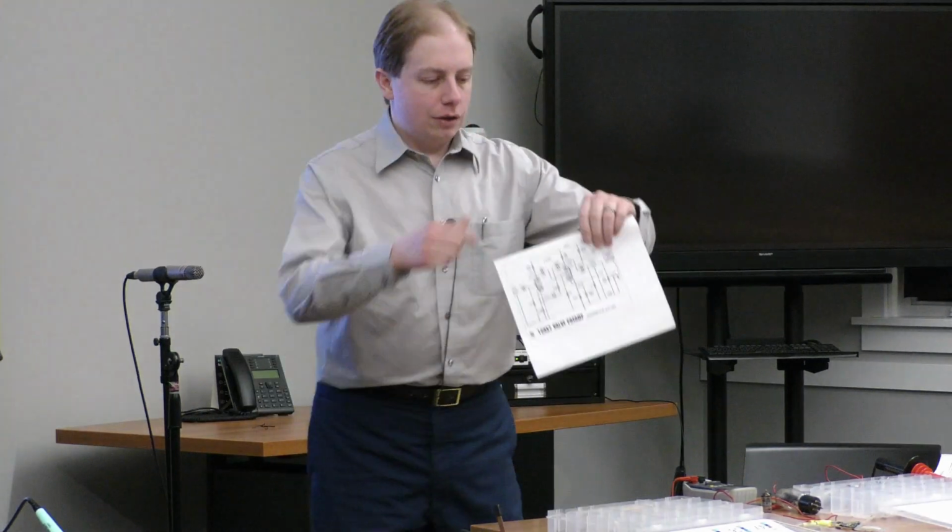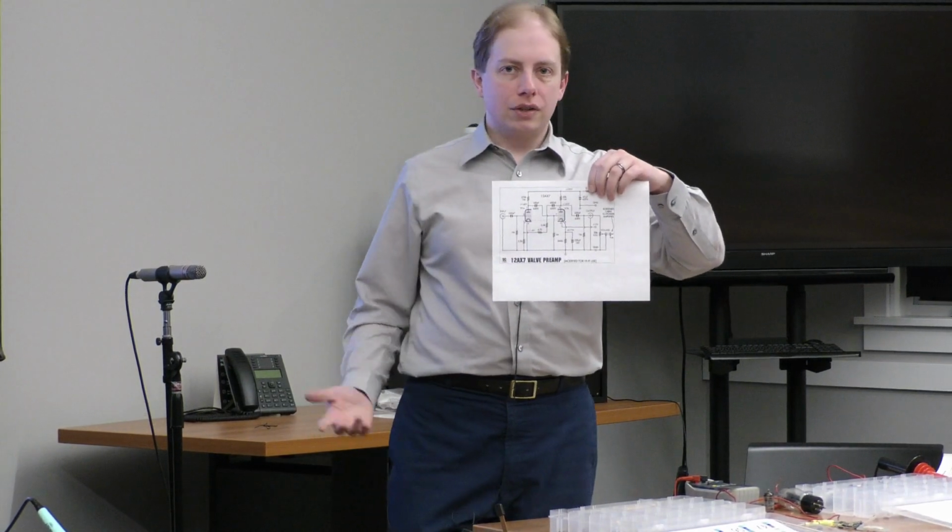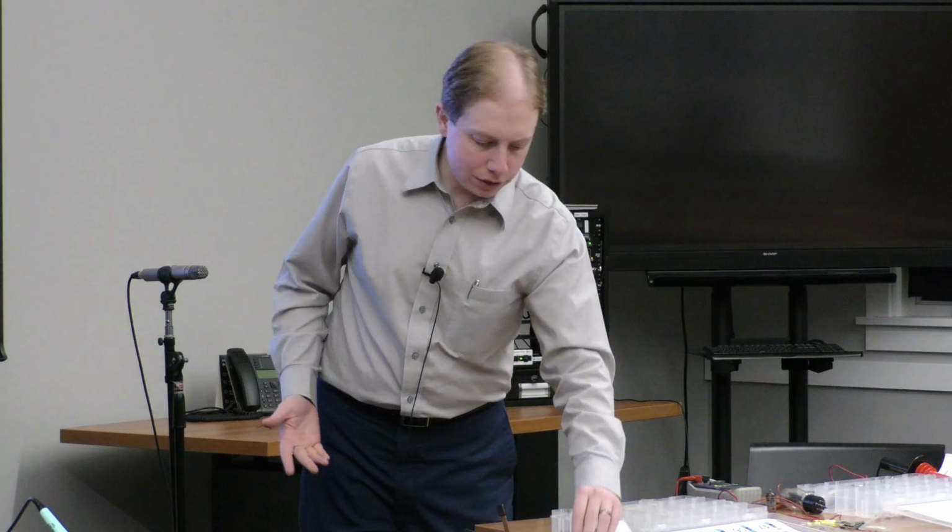In the United States, this little zigzaggy line is a resistor. But honestly, on international schematics, you'll see it as a little square box. So you have to keep that in mind. And even over the years, if you're looking at older drawings, it's not unusual for them to change how the symbol is drawn. But after a while, you can figure out what it is.